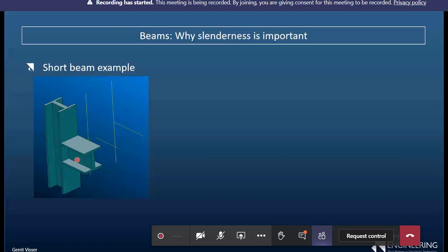At first glance, when you look at this kind of a structure, and even if it's part of a larger structure, it looks like a beam. We want to model it like a beam. Now if I model this using curves to show where the centers of the beam sections will be, that section there at the back with that thing stopping there represents this beam and that beam. Now what do we do between those two? And that's exactly one of the major reasons why we have to be careful when we model with short beams, because what I do there critically changes how the structure will behave.